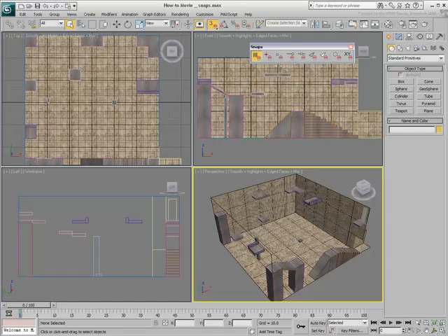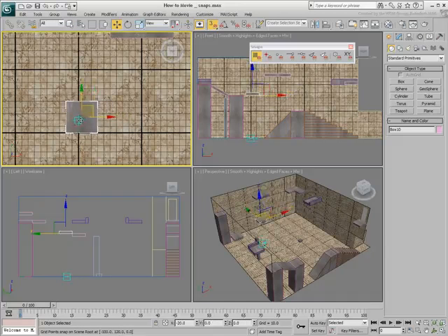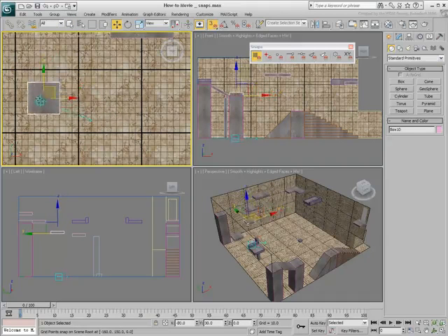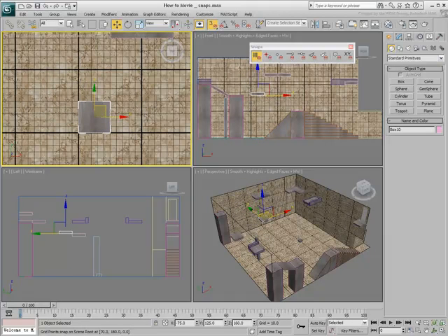Using the Snaps toolbar, you can then choose which points in space you would like to snap onto. In grid mode, you can only snap to intersecting lines on the construction grid. The texture map in this example has been set to match the existing construction grid. Perhaps more importantly, you can snap onto geometry points such as objects' pivot points, vertex points, midpoints, edges, faces, and so on. Arguably one of the most valuable snap options is vertex, which lets you snap onto any intersecting point between two or more edges.